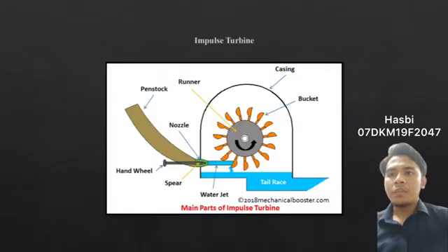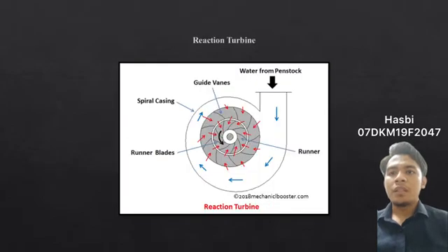The superheated steam is projected at high velocity from fixed nozzle in the casing. When the steam strikes the blades, sometimes called buckets, it causes the turbine shaft to rotate. The high pressure and intermediate pressure stage of a steam turbine is usually an impulse turbine. The steam expands through the fixed nozzle, where pressure potential energy is converted to kinetic energy. The high velocity steam from the fixed nozzle impacts the blades, changes direction, and undergoes further expansion.